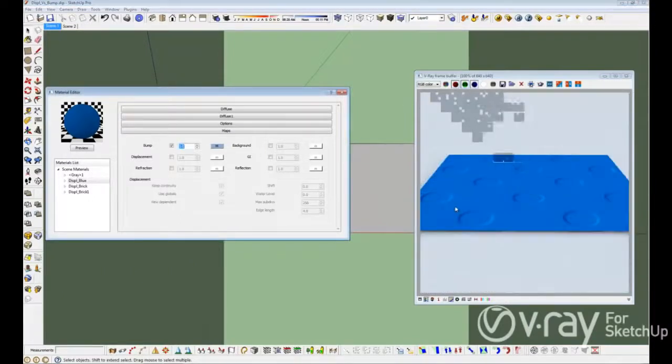The multiplier controls the depth of the mapping. Notice in the rendering that the bump mapping adds some detail to the image. To increase the depth of the bump mapping effect, increase the multiplier to 20. Let's render this scene.